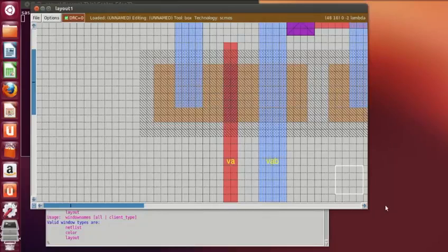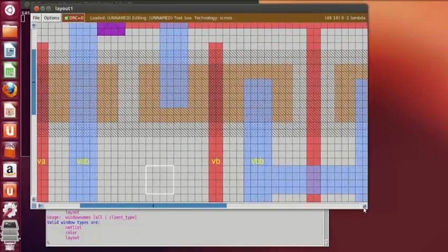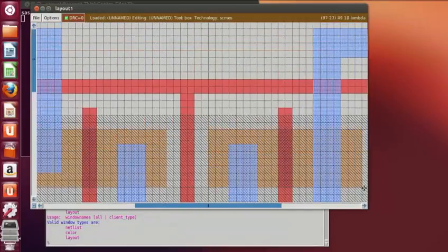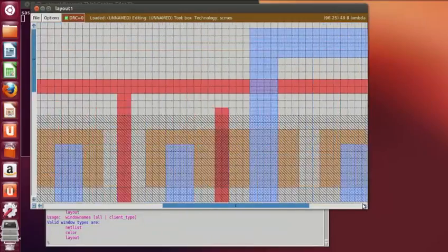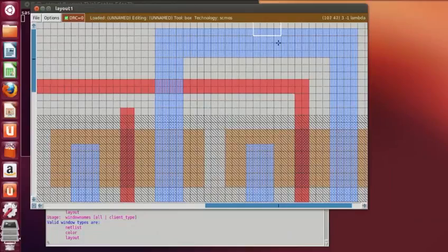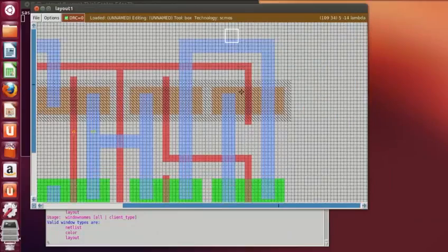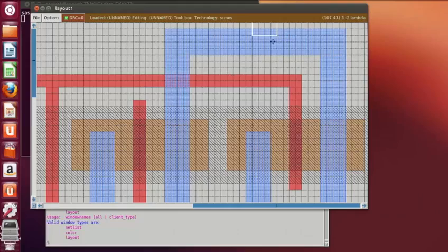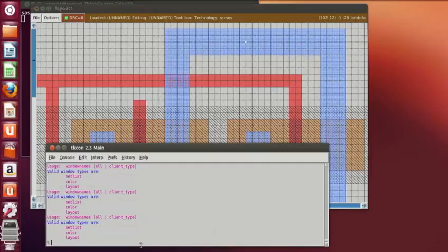Okay, before going to contacts, we can label the other terminals left. The other left is only the output. So this is the output. So select, right click, and then label V out.